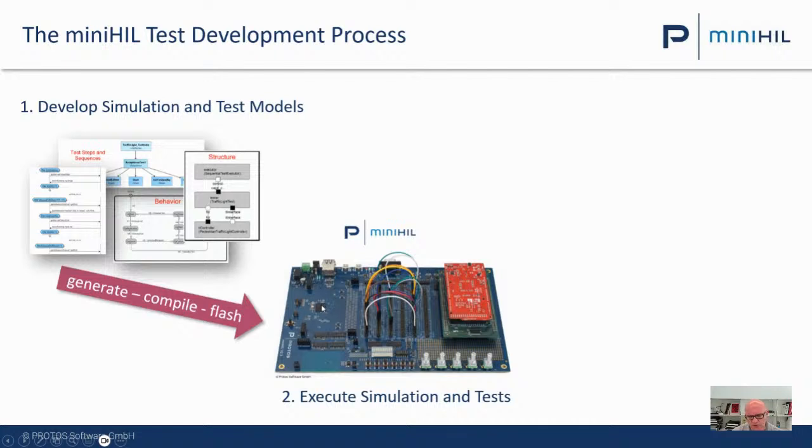It's actually a microcontroller Cortex M7. Why are we using such a small Cortex-M processor? Because it needs to be fast and deterministic. So if you want to simulate a motor controller or motor for a motor control system, you need 20, 30 kilohertz. And that's something you cannot do on your laptop, for example. If it's hardware in the loop, you need to have hard real time. So that's why we use a hard real time system here. And here you see on the right, we have a different processor. Here, for example, an Aurix from Infineon. Again, the patch panel, and here the test cases and the environment simulation.